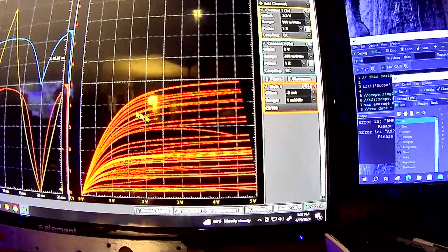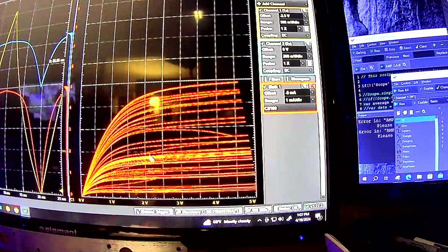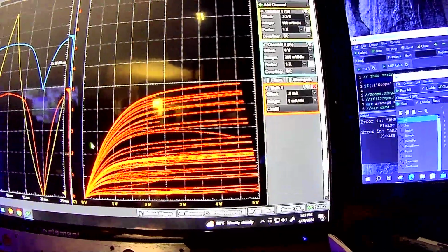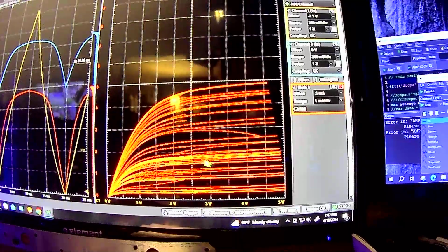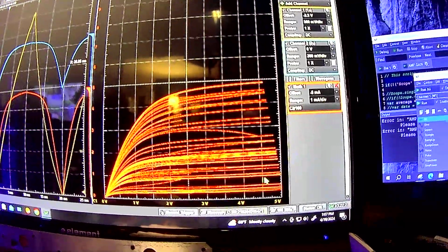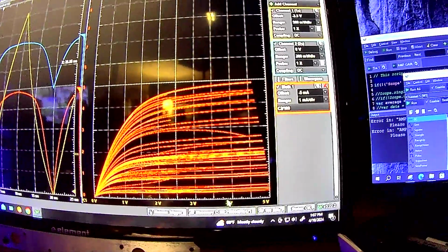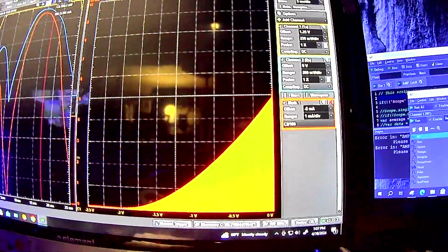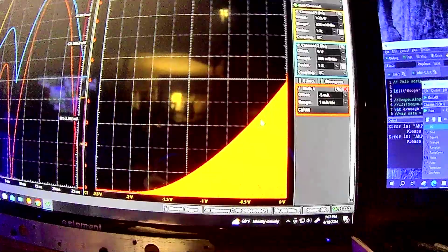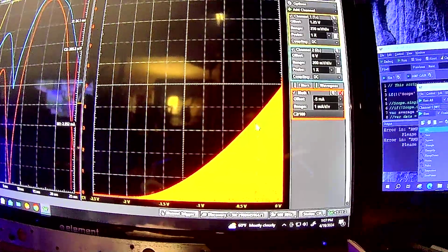So if you were to draw a load line from like 5 volts up to, let's say, 3 milliamps, you want to avoid this region because it's the ohmic region, right? And here's the more linear region. That's what you'd want to operate in. And if you recall, that's sort of where we want to bias things over here, up in this region, as far as the gate voltage to current.